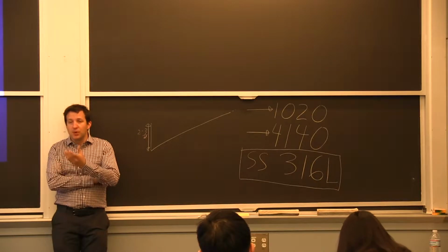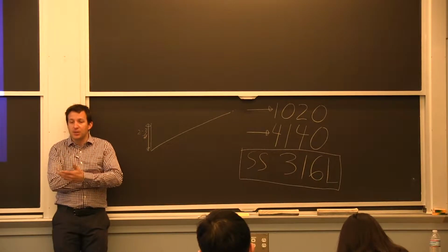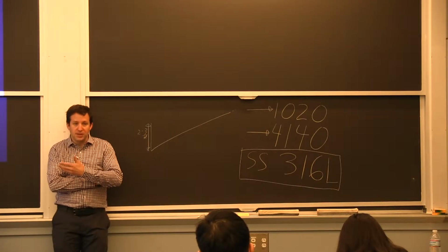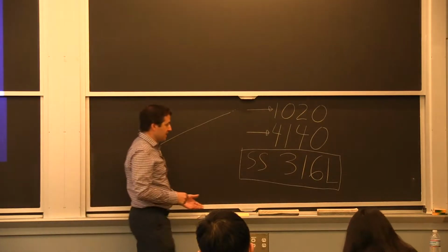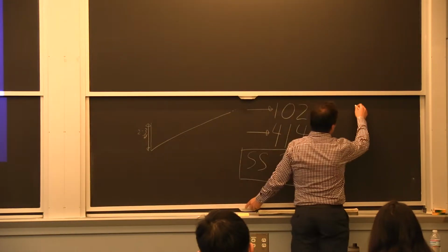It's not so much in the weld pool, because a lot of times you can come in with a filler metal that has so much chrome and nickel that it will be corrosion resistant. What matters is the metal that's in the heat affected zone right next to it.